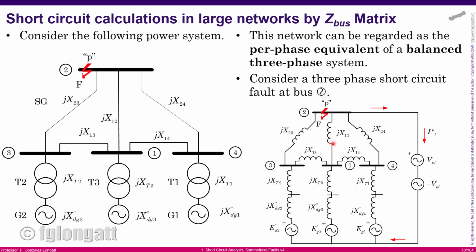On the right hand side, what I am presenting is the reactance diagram during the fault conditions. The fault is a three-phase fault applied here at point P, and you can see that we can use a beautiful mathematical trick. There are two voltage sources over there, one positive, one negative. The total voltage across the terminals is 0. That represents the short circuit.